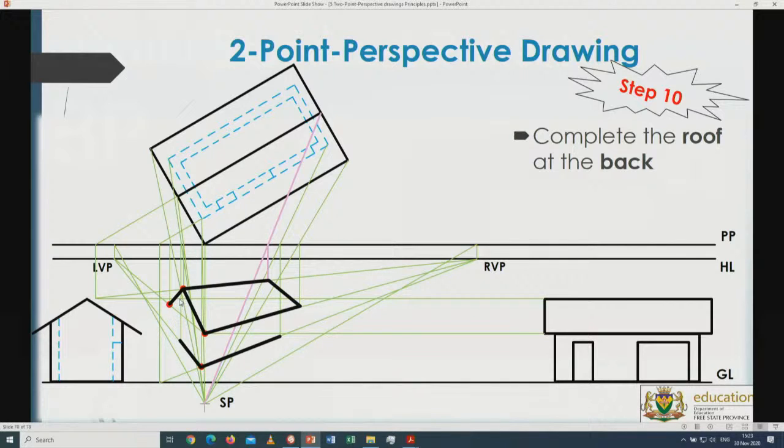And like I said, there's no solid line in between here. I need to find out where exactly is that stop or end point of this wall. Now that's the end point of the wall. I can extend the line going downwards, find the height of it there, and then from there on disappear to the right, and somewhere on that line, and where those two lines intersect with that end of the wall over there, that's going to be the point. So we can do it, or we can also extend it towards the front part, towards this part, going downwards, get the height of it, which is that point, disappear. In this case I went to the right, disappear to the left, somewhere on that line, I can simply drop off that line and find the intersection point.